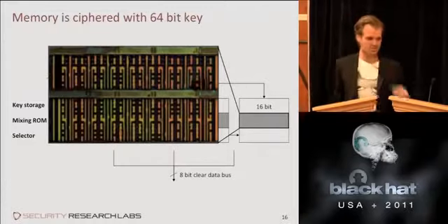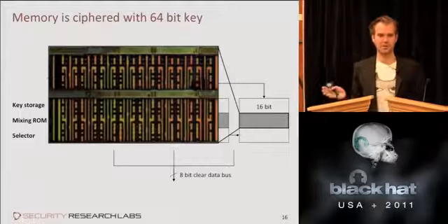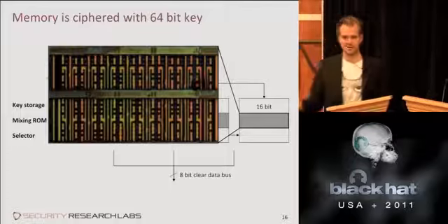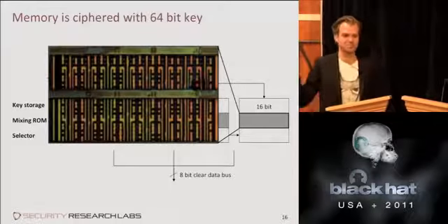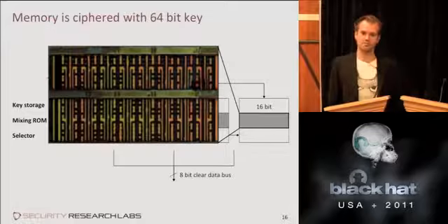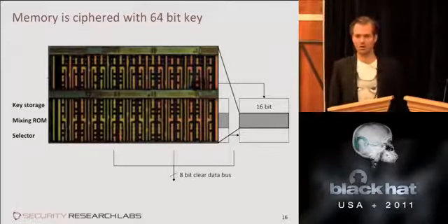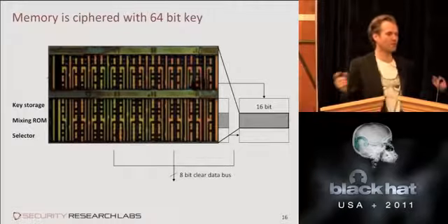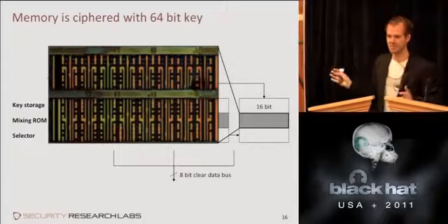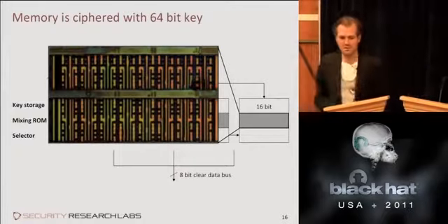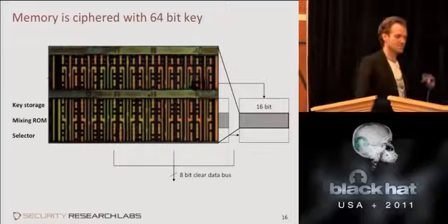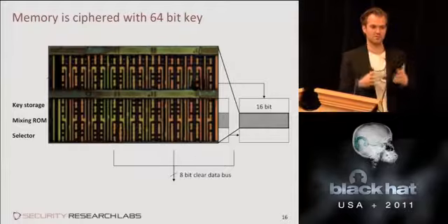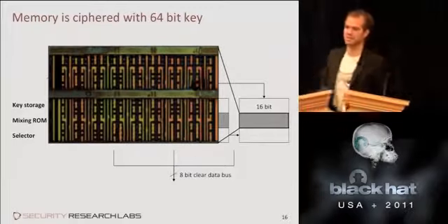Not by every chip, but every version of the chip, and clearly by every customer. So no 2 customers and no 2 versions of any operating system you put on here use the same decryption function. Neat idea, only the way they differ is by a little ROM, and we already know how to read out ROM. So it's one more unknown you have to fill, but you can read it out in the same step as the other ROM you want to decode anyway. So it's neat that they try to make it different and force people to reverse engineer it over and over again, but doing it on this layer is probably not so effective.